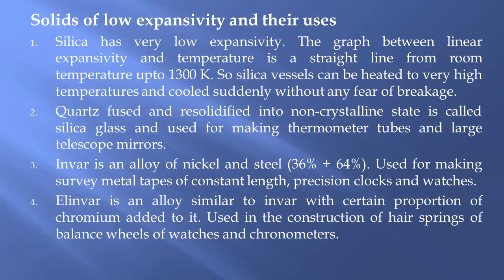Next, solids of low expansivity and their uses. Silica has very low expansivity, and from the graph which is drawn between the linear expansion and the temperature, we can find that it is a straight line from room temperature up to 1300 Kelvin. So silica vessels can be heated to very high temperatures and cooled suddenly without any fear of breakage. When quartz is fused and re-solidified into a non-crystalline state, it is called silica glass and it is used for making thermometer tubes and large telescope mirrors.